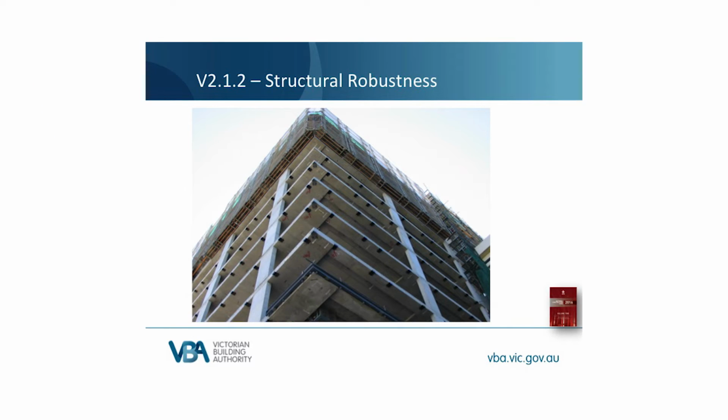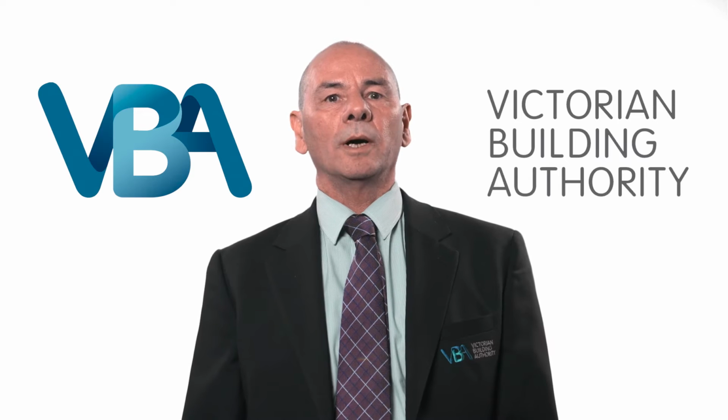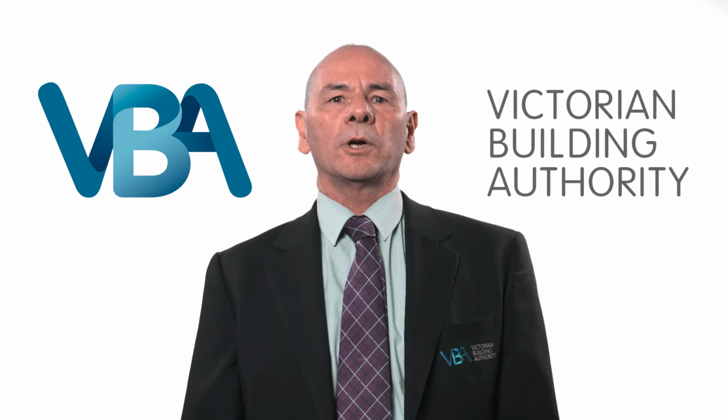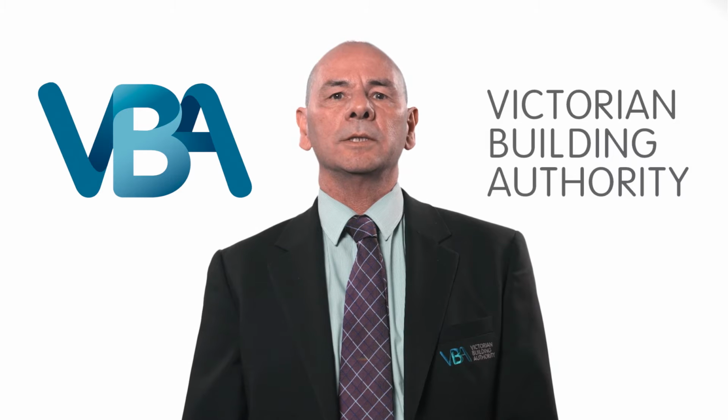The first new verification method is for structural robustness. This verification method is directly linked to performance requirement V2.1.2 in Volume 2, which in a nutshell requires that if part of your building structure breaks, the damage shouldn't extend beyond what is reasonable for that building. For example, if a column in a car park breaks, the whole car park must remain stable.